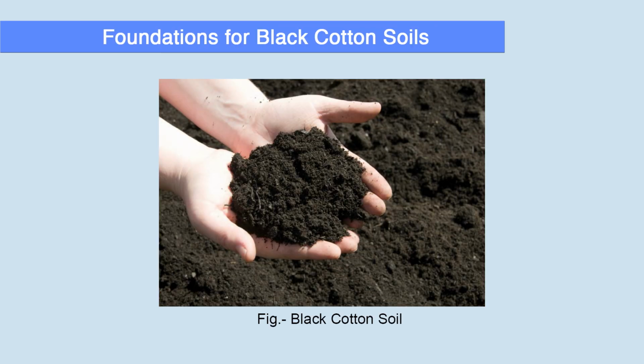Then the next is foundations for black cotton soils. Black cotton soils, classified as expansive soils, present unique challenges for foundation design due to their significant shrink swell behavior. These soils contain a high percentage of montmorillonite, a clay mineral that causes the soil to expand when it absorbs moisture and contract when it loses moisture.